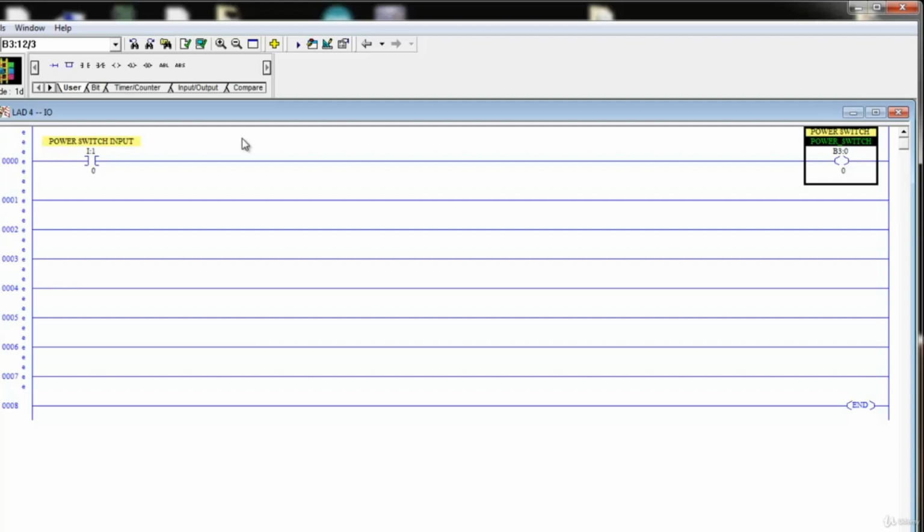And it's a favorite pastime of electrical engineers to remap I/O on a whim, or just to make it look better, or to make the wires fit better in the control panel. For whatever reason, if we need to move our power switch from channel 0 to channel 5, we want to make that change in exactly one place.